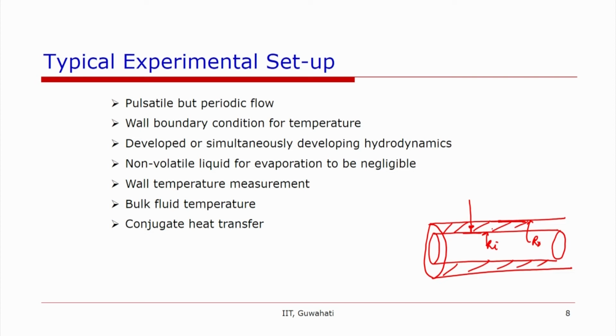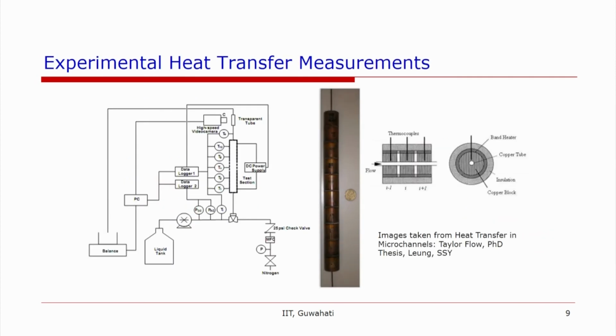So, in general, when one puts temperature sensors here, one can obtain an analytical solution for the conductive heat transfer in this direction, or if one wants to take into account the axial heat transfer also, then one can have full 3D simulations to look at the effect of conjugate heat transfer. Okay. So, all these factors need to be thought about when performing the experiments.